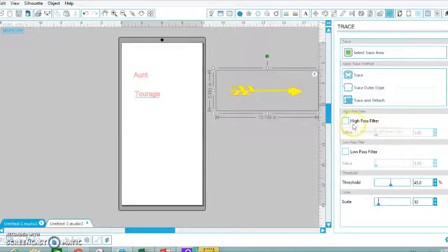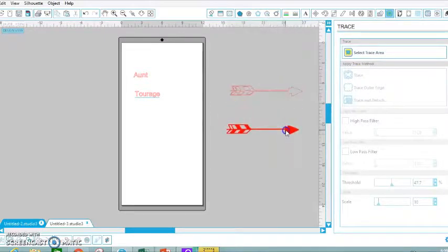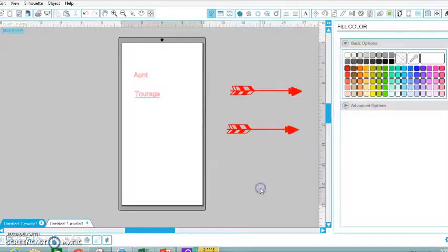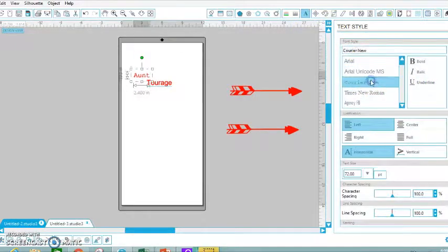and then you basically want to highlight everything that is a solid fill in yellow. So you just play with the proportions until you get things highlighted as much as possible without it looking fuzzy. Then you select Trace, and it gives you a duplicate outline. Here I just fill everything in red because it's easier to work with that way. I know I want both of these to be solid colors, and it really just helps me with the contrast.